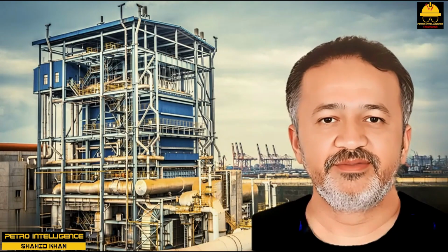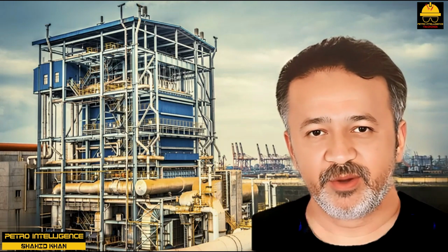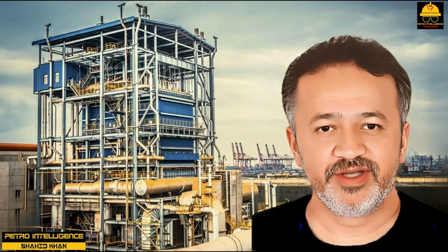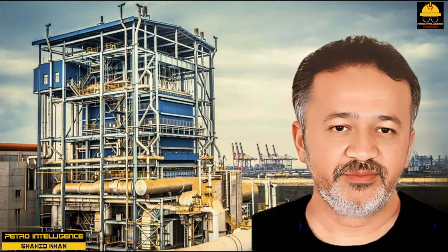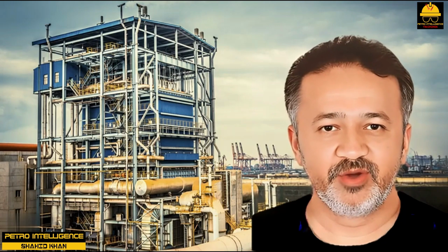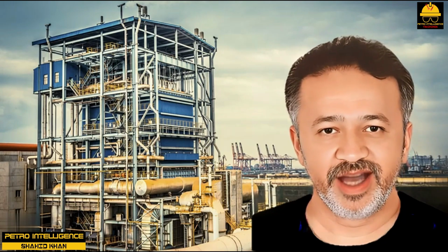Smooth high alloy tubes. The use of smooth high alloy tubes in otherwise corrosive service has been widespread practice since the 1950s. Tube metallurgy is selected to minimize corrosion while in service. The tubes therefore maintain their smooth, shiny finish. Without sites for fouling deposits to attach or accumulate, the clean heat transfer coefficient is maintained. This idea has been used with success in refinery catalytic cracker feed preheat service, placing slurry oil on the tube side and vacuum gas oil on the shell side.